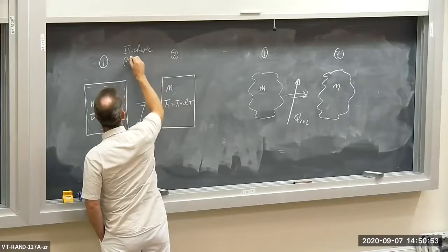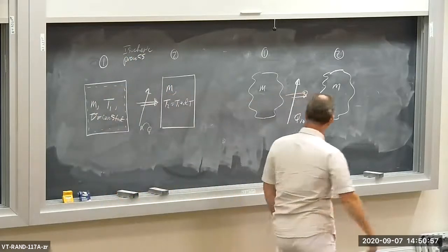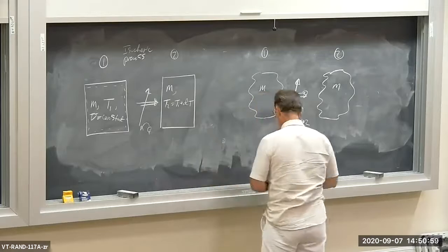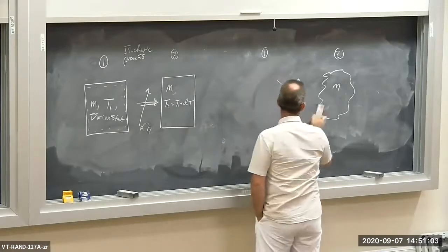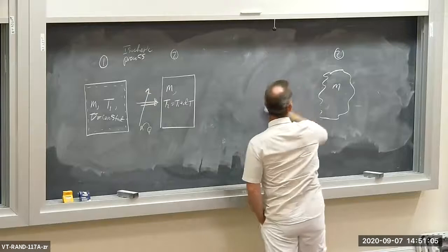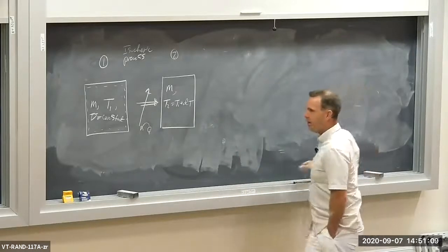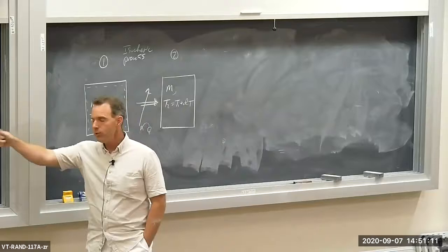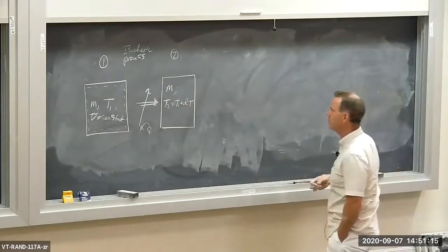Same thing as before, except we have a constant volume process. Isochoric process. What's isochoric? Constant volume. So we have a new specific heat defined because the path is now different. Instead of traveling an isobaric process, we're now traversing an isochoric process.